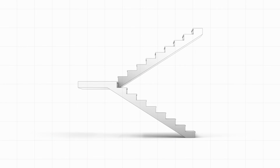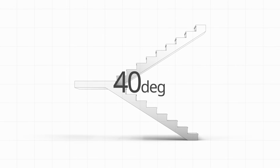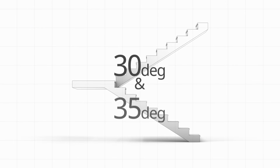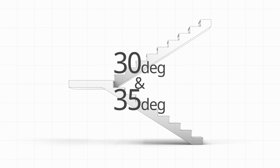Maximum allowable stair slope. The slope of the stairs should be adjusted in such a way that it doesn't put excessive pressure on the legs, ensuring that movement on the stairs is comfortable and safe. According to Neufert standards, the maximum slope for stairs is 40 degrees, but the preferred range is between 30 and 35 degrees for greater comfort. This slope allows individuals to move up and down the stairs without experiencing excessive strain.